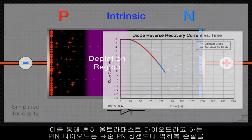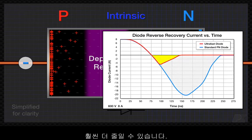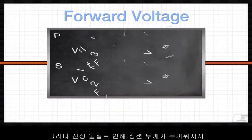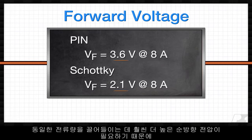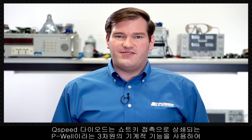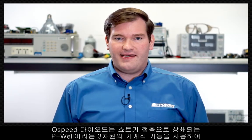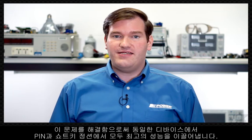This allows PIN diodes, commonly referred to as ultrafast diodes, to have much lower reverse recovery losses than a standard p-n junction. But the larger junction thickness brought by the intrinsic material requires a much higher forward voltage to drive the same amount of current, causing increased conduction losses and lower efficiency. Qspeed diodes solve this problem using three-dimensional mechanical features called P-wells, offset by Schottky contacts, to get the best of both pin and Schottky junctions in the same device.